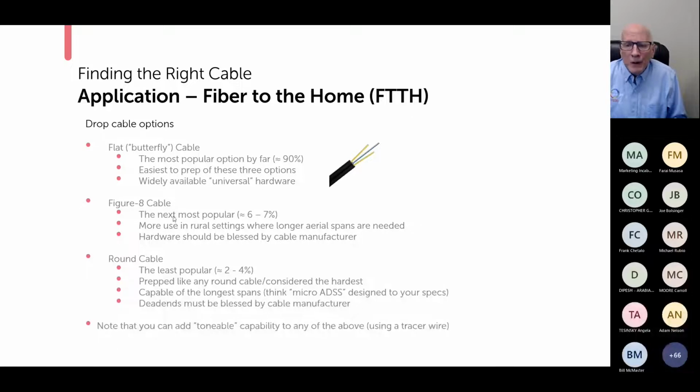Figure eight cable, basically a small version of the figure eight cable that we talked about before, is the next most popular. You see roughly 6 to 7% of what we supply is figure eight type. We see this used more often in rural settings where you need longer spans. And in this case, you can't just buy any hardware and use it.